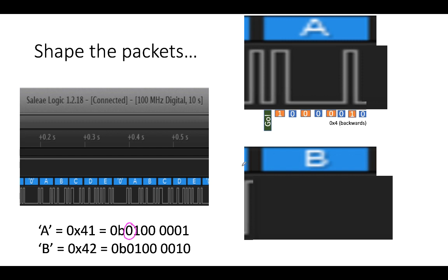Okay, and as you can see, this is 4. It's basically 4 backwards, from this visualization. And then there's a stop bit. We have one stop bit, and that stop bit is a value of 1. So that whatever's interpreting the data, the 8 bits that are coming through, it knows that we're now done with those 8 bits. So it knows that there's a start, a go, and a stop.